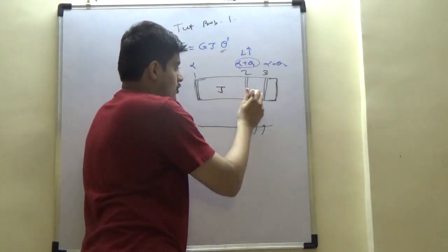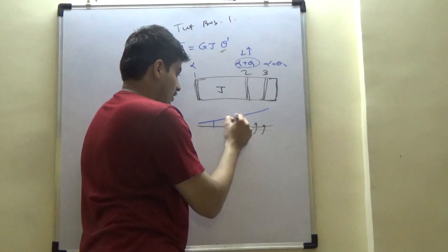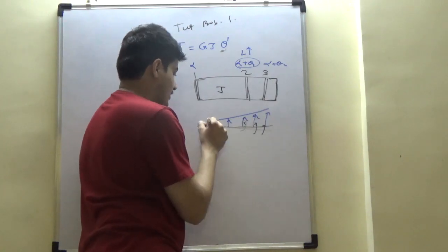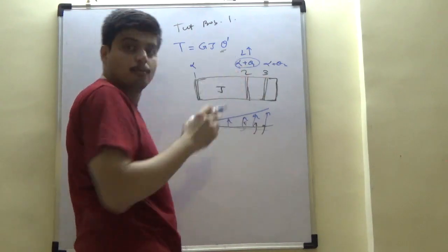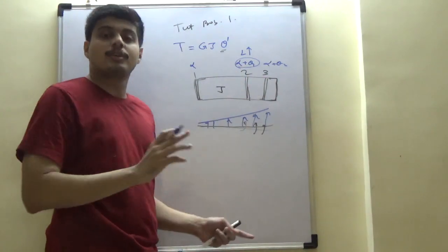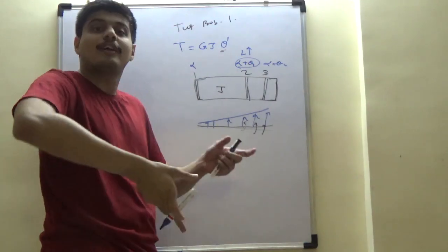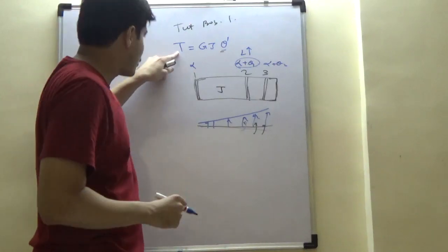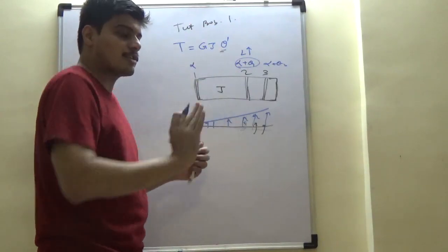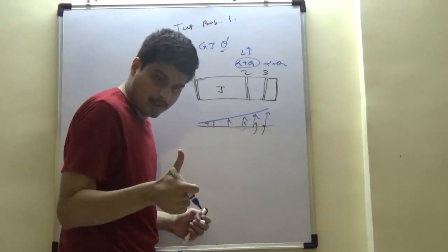Then lift has gone up locally here, which means lift no longer is constant but has suddenly gone up something like this. Added lift is going to create a further moment, which may further twist it. So there is a coupling involved. This is called aeroelasticity, and that's the role of structures. So with this torsional theta dash, the twist that the wing brings in, the lift distribution becomes non-linear.